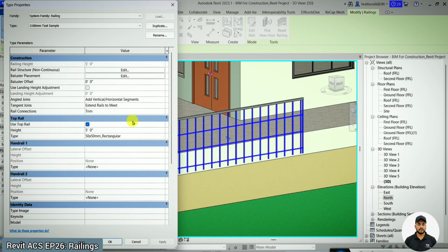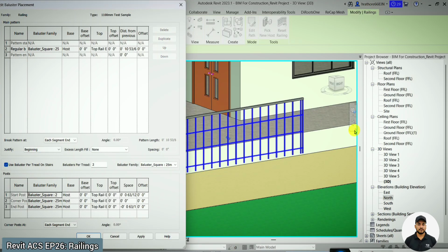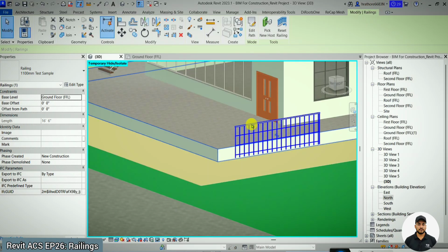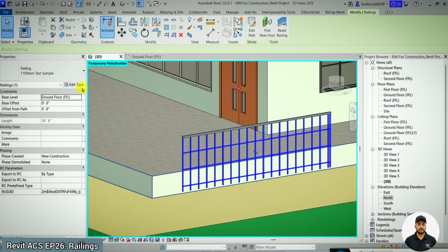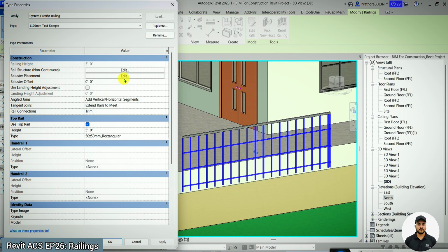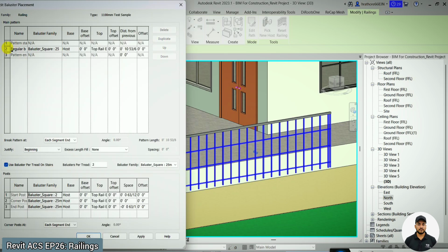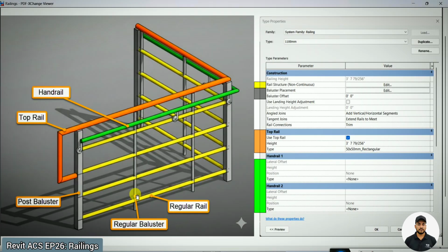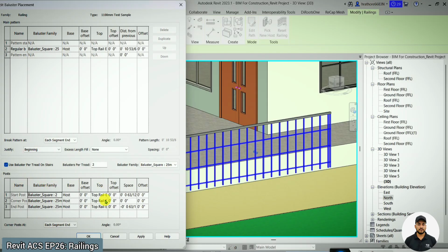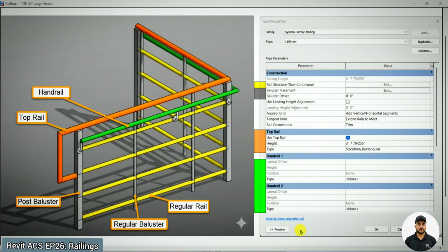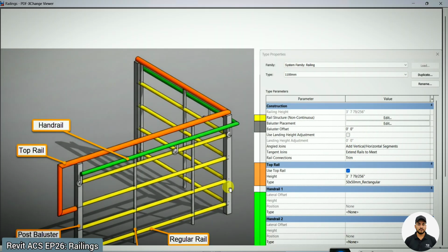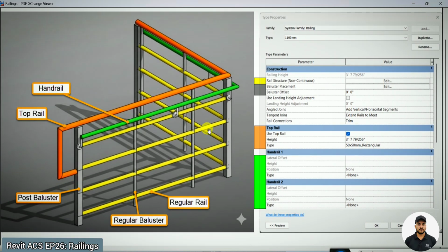Now let's move on to the different parameter, that is we are having the balusters. Now we need the baluster in the starting of this railing and the end of this railing. Okay, so how you can control them? So for that one you have to go to balusters. Here in the balusters, the top pattern you are having is the middle balusters, that is this one, that part regular balusters. Okay, and the below part you can edit here is the main, that one will be the post balusters. Okay, post and in middle if you are having a baluster, then the post, middle and end balusters.